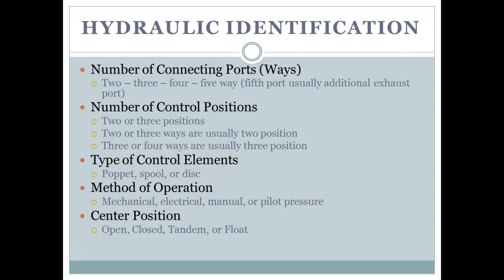You pressurize it first. But the problem is, as soon as one of those valves or actuators shifts, then you're going to lose a little pressure. And that's why we call pneumatics spongy. But what advantage does pneumatics have over